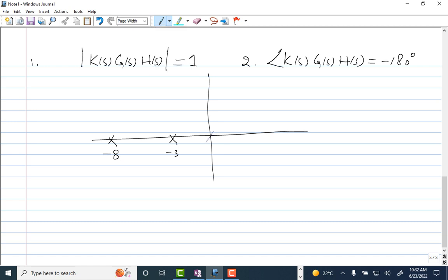I know that the PI has one pole at the origin and another zero here, so I call this location P_PI and similarly this location Z_PI. I need to find this location. Now I choose a black color, and as we know this is minus 5, and we make this our closed loop pole desired location. So this was 5.55 j.